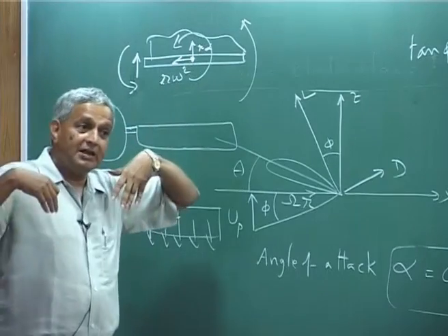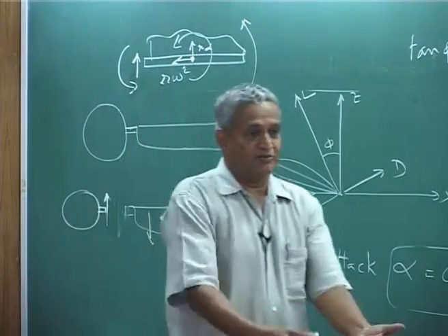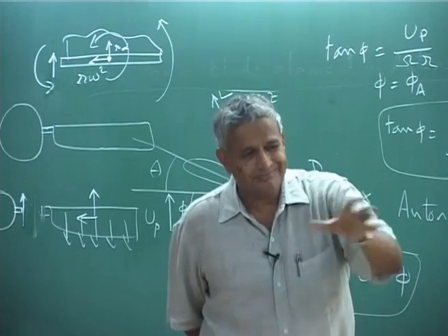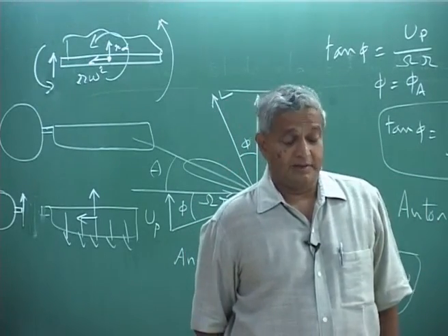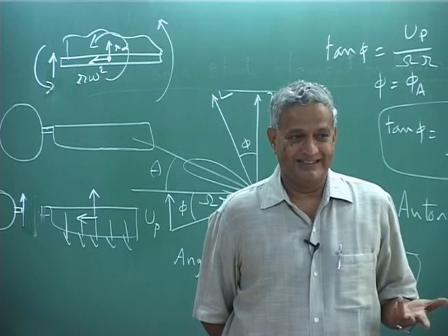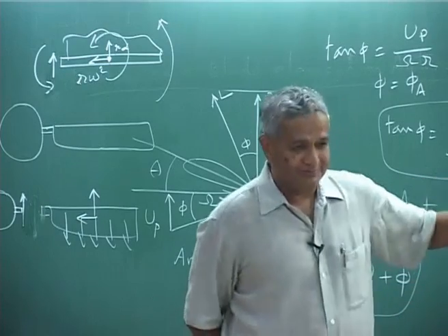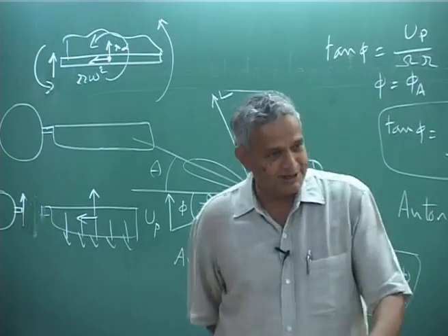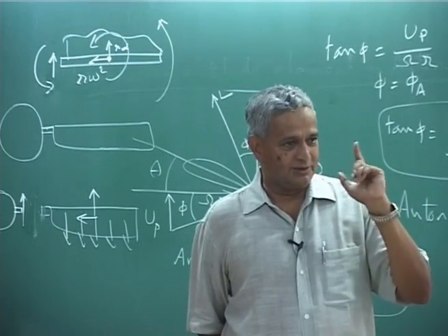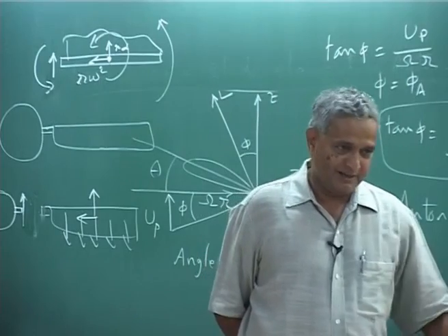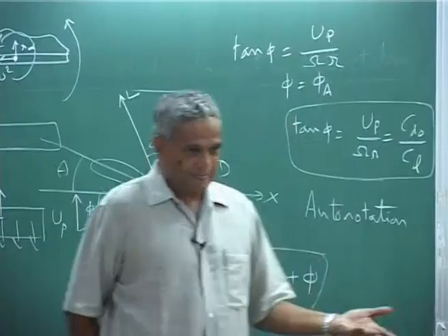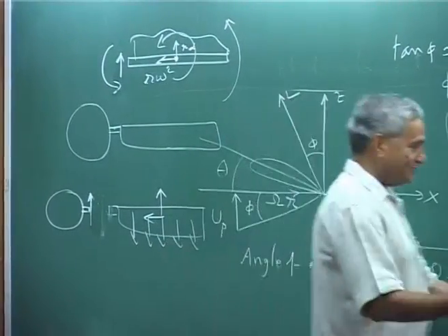So you need to see whether every condition will be satisfied. Usually torque is 0, that means your RPM is okay, take it. But I don't know whether the forces are really balanced to 0, though it may come very close to 0. There will be some redistribution of the loads, because you do not want the rotor to change, that is why the pilot dumps the collective. He may not hold it at the same value, he may keep changing it a little bit.